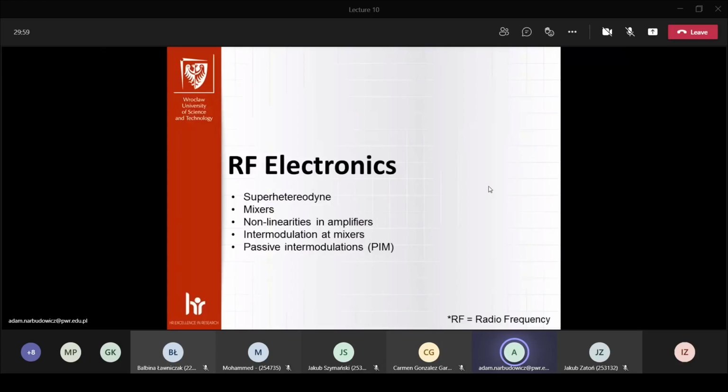So hopefully by now you should realize, especially with what we spoke about in the previous slides, that modulation requires the creation of components at new frequencies. That's why we need nonlinear components. Okay, so presumably either diodes or preferably transistors. You cannot do modulation, at least classical modulation, using only passive RLC components.